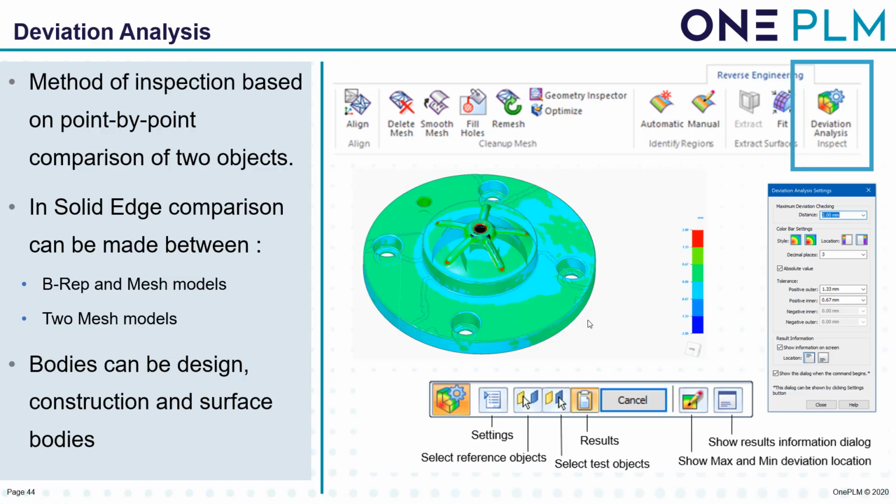So best of the rest. So we've got deviation analysis. So when we do reverse engineering, we want to see how different our reverse engineering item is in relation to the original item. So I want to see, has that moved 2 mil? Has it moved less than 2 mil? And we've got the different values on there, so we can see the difference between those. So we know actually I've oversimplified that, and I want to go and redo that component.